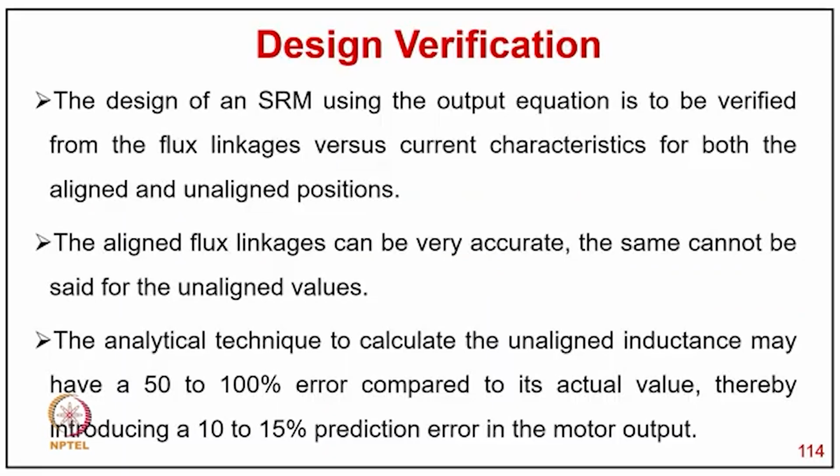Now coming to design verification and performance calculation of SRM. The design of an SRM using the output equation is to be verified from the flux linkage versus current characteristic for both the aligned and unaligned positions. The aligned flux linkage can be very accurate. The same cannot be said for the unaligned values. The analytical technique to calculate the unaligned inductance may have 50 to 100% error compared to the actual value, thereby introducing a 10 to 15% prediction error in the motor output.